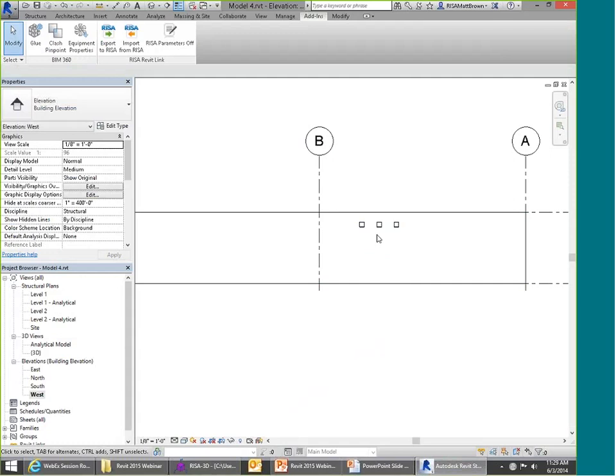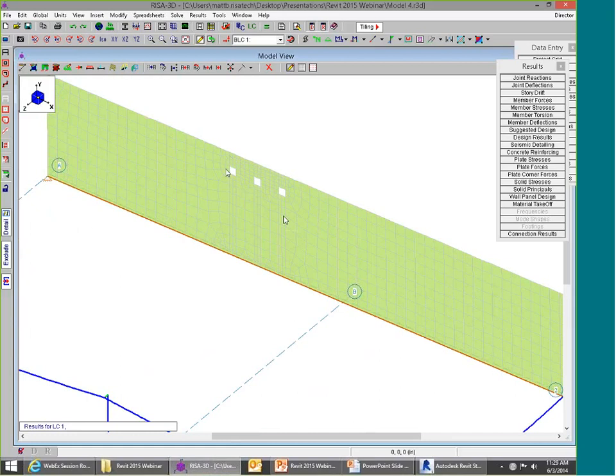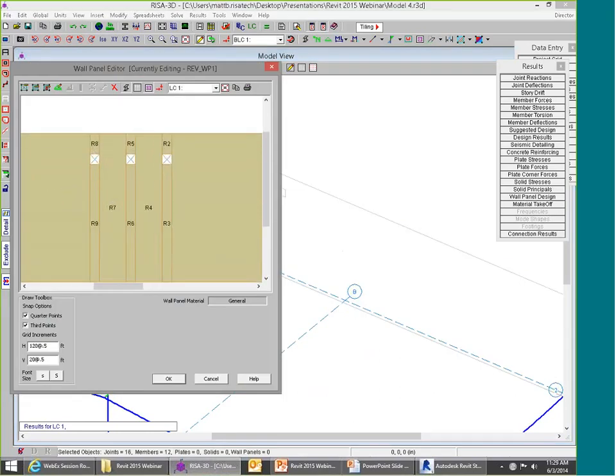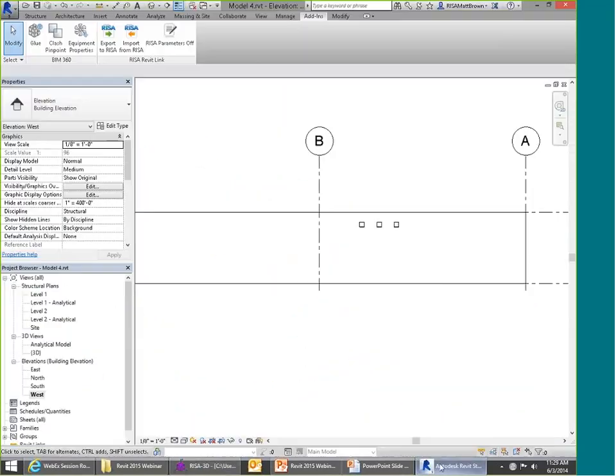You don't want that as part of your structural model. That creates a whole lot of excess complexity to the way this is done. I mean, even the region design here, we're now going to get separate rebar design in between each one of those openings, when in reality, these are structurally insignificant openings.